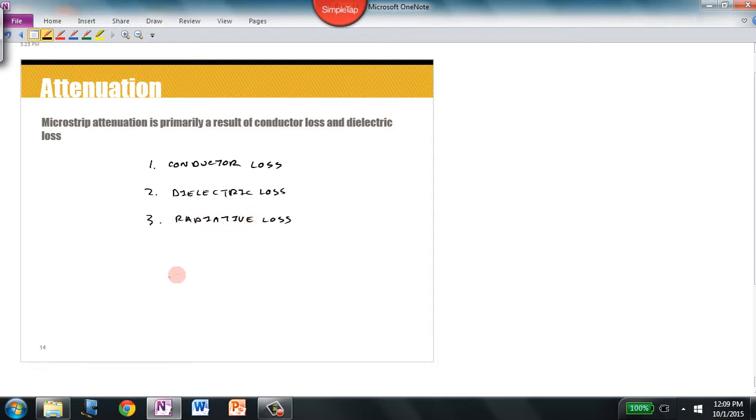If I have a perfectly flat conductor, radiative loss typically won't occur. Radiative loss occurs when there are irregularities on the surface of the conductor. These act as tiny little antennas launching electromagnetic waves from the surface, and therefore power gets directed out of the T-line and into the electromagnetic wave. That can also occur if there are right angles in the transmission line.